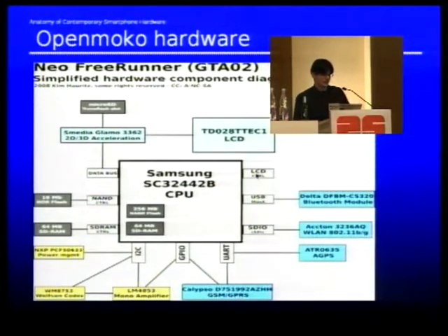Yeah, we have an LCD controller that is obviously connected to the LCD, not disconnected. No, it's actually true. The LCD controller is not used. The built-in LCD controller of the SoC is not used in this hardware revision, but there is a graphics accelerator, in quotes, connected to a display module. This is the LCD display. And that one, again, has an SDIO interface, which connects to the SD slot, because, well, the SDIO controller here is used for the Wi-Fi interface. So you see the kind of problems.